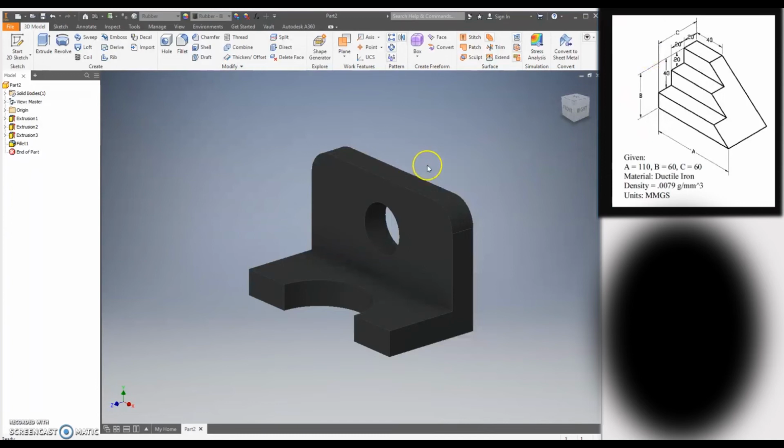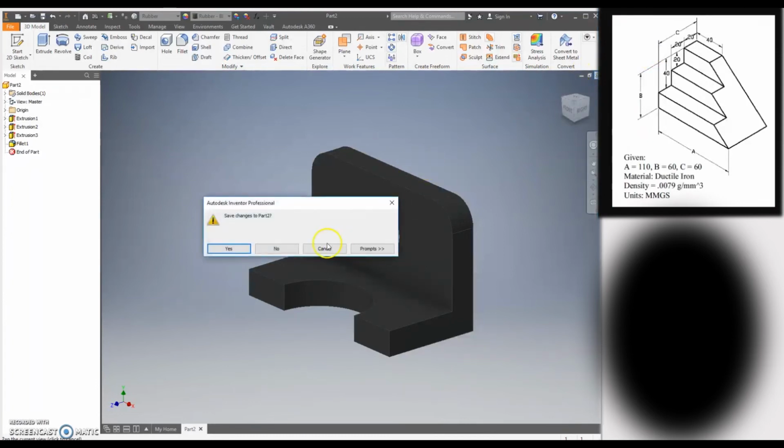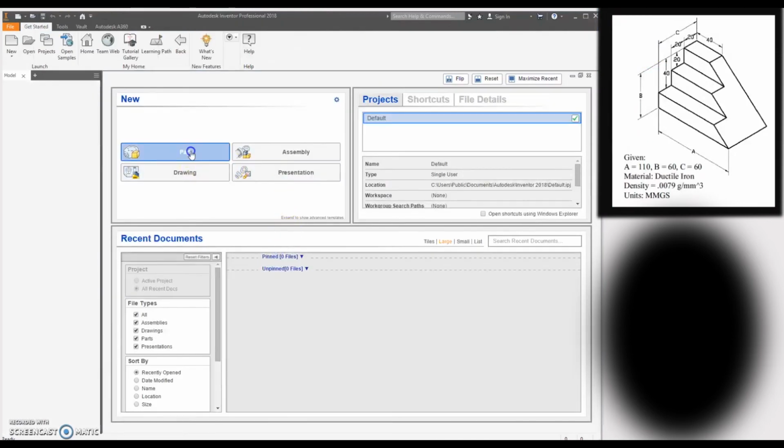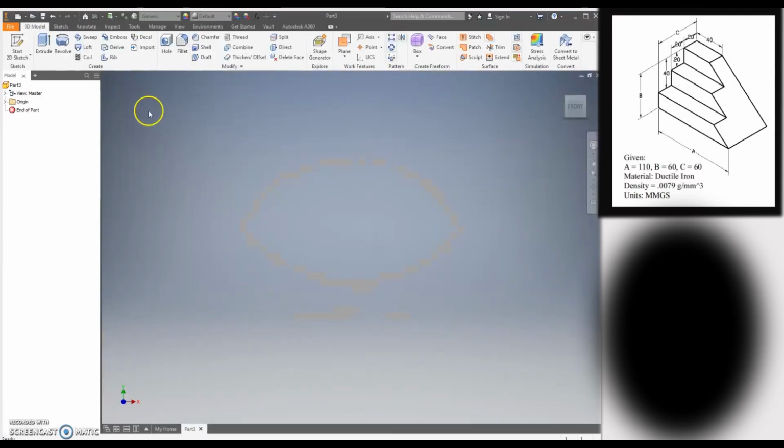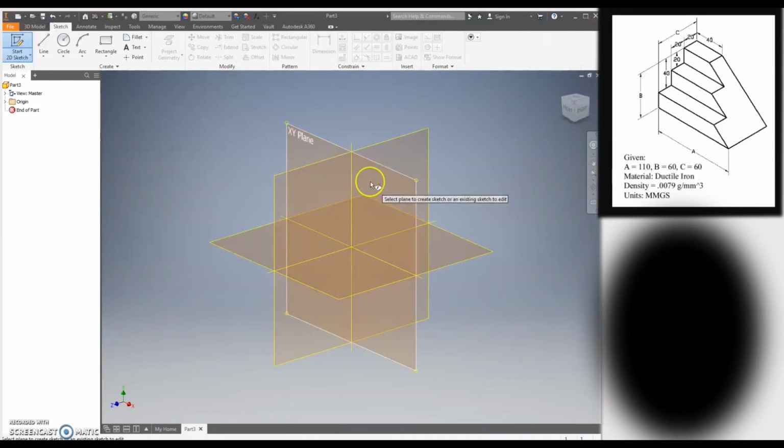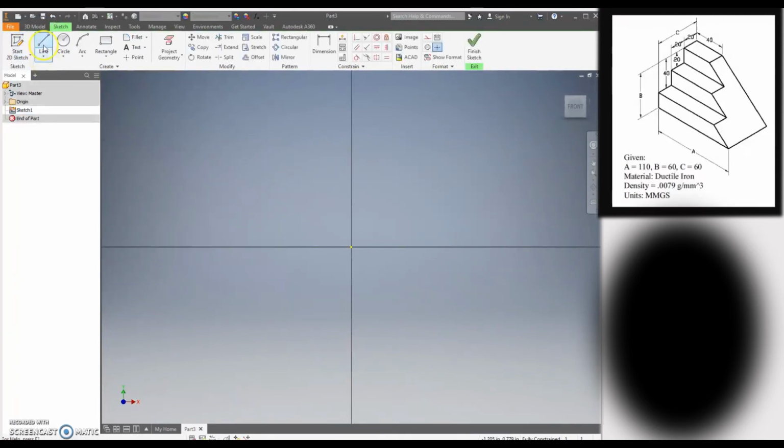A lot of students have trouble with the slanted staircase and just how to attack this one. So I'll just show you how to set it up. Won't even dimension it. Just give you the basic shape of it. So sketch, and you're going to sketch that back face. The back face has the most detail. I see a lot of students like to try to sketch that slant, and you can. You end up with this big block, but there's a lot of cuts in the stairs that you can just knock away right away. So we sketch that staircase as if that was the back right there.